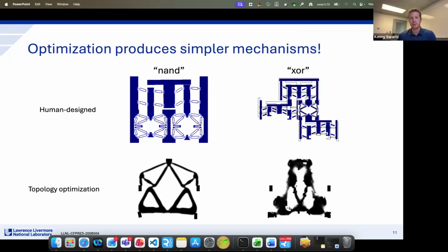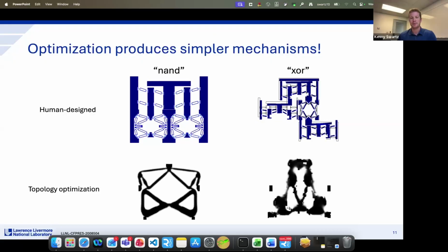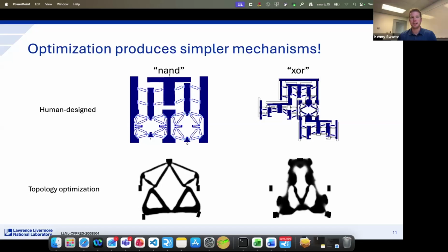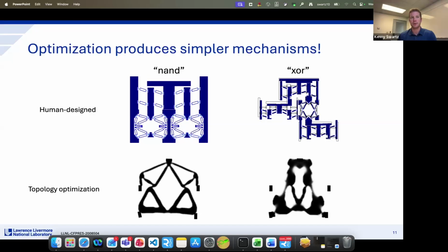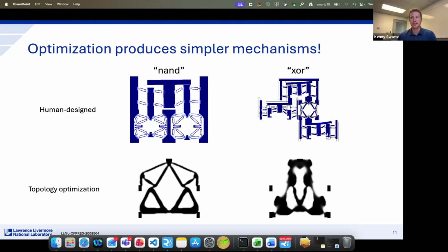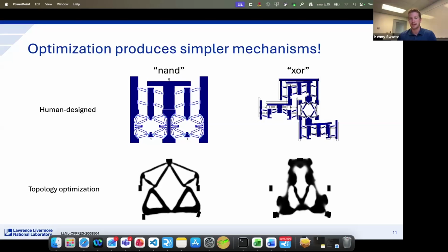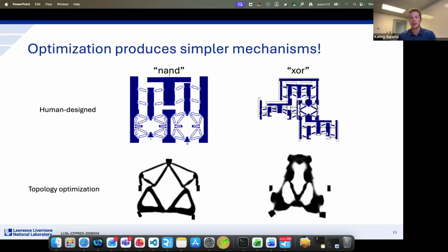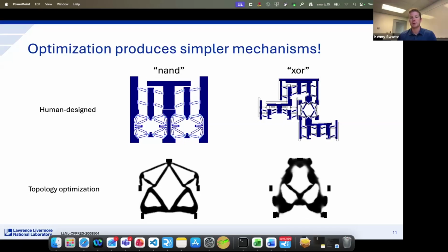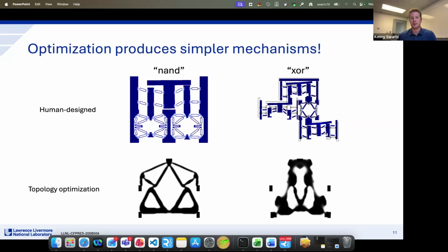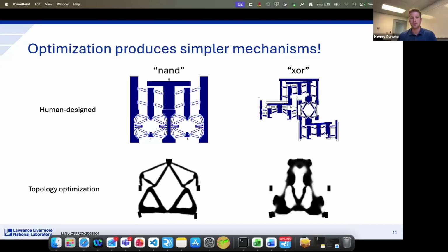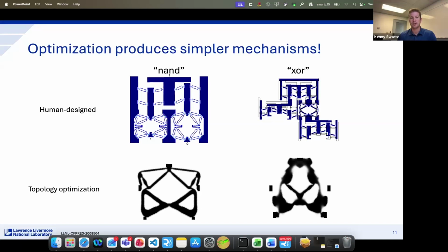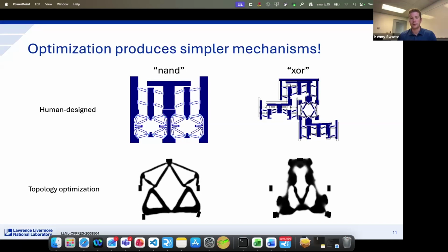So I'm looking at a couple of different techniques for how to put a minimum feature size in from a manufacturing point of view, which in a sense is a proxy for avoiding damage, because we know if a feature isn't tiny, it's less likely to break right away. I do think a next step in this work is to put in, whether that's reducing the yield stress or a damage model or something like that. I do think we want to make sure that these hinges aren't going to break right away.